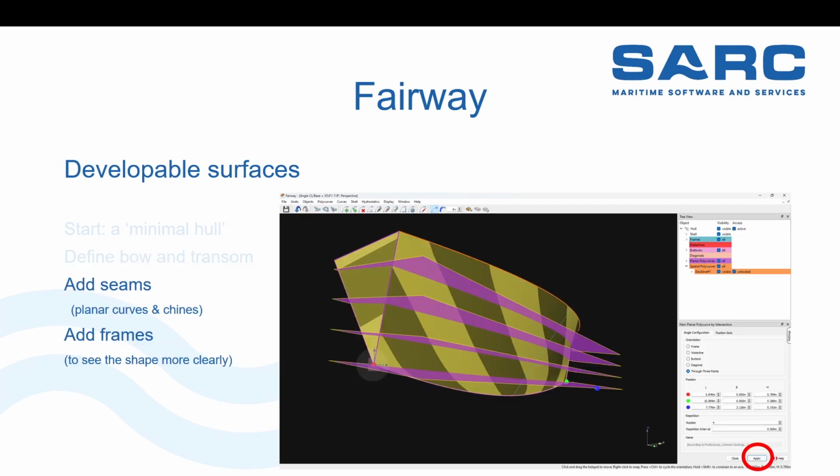Okay. Then I added a few, well, oblique, it's not even water lines, but oblique planes. I just picked the knuckle here and this knuckle there and stacked a few on top of each other with a distance of 0.5 meters. And the third point here, I just visually checked whether or not I was happy with the, well, let's say the sideways heel of these planes. They are oblique in all directions actually, but it's still planes. And you can interpolate, well, a bunch of them in one go.